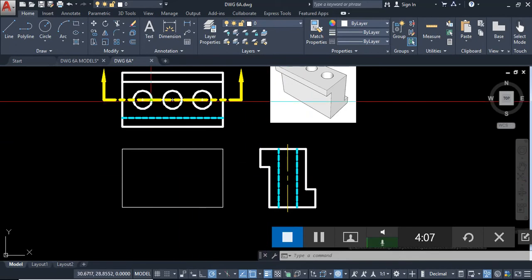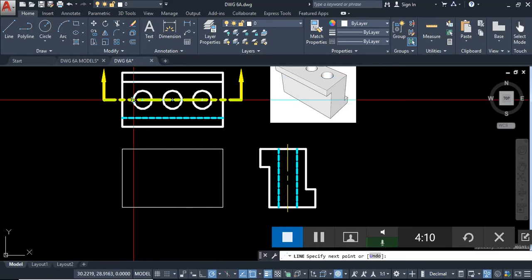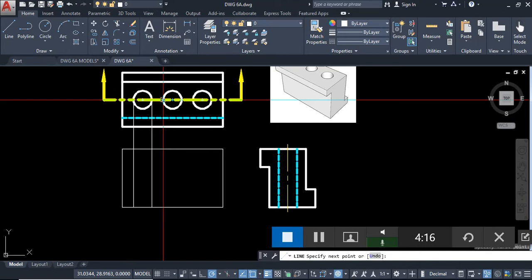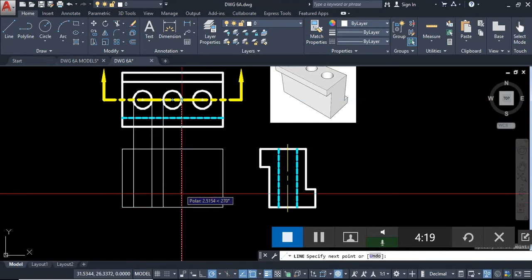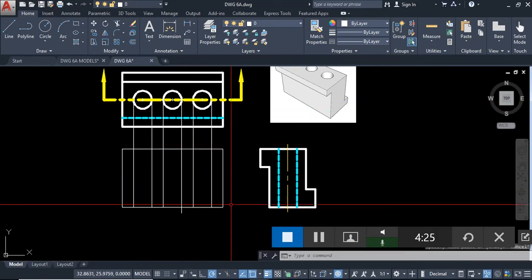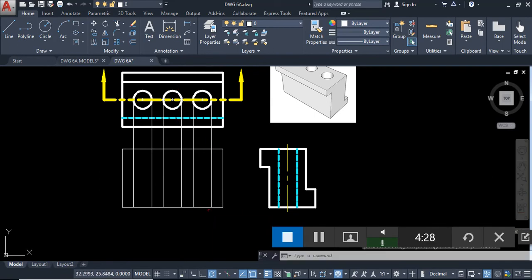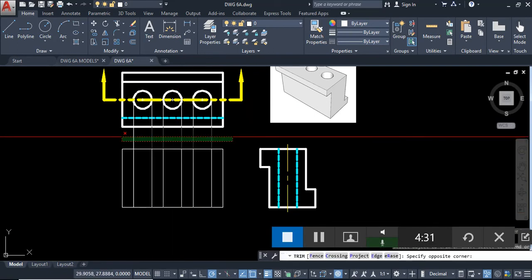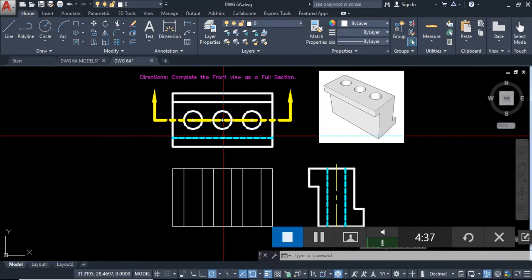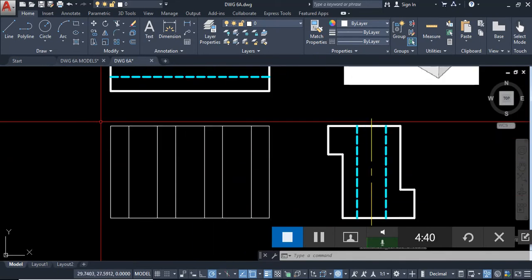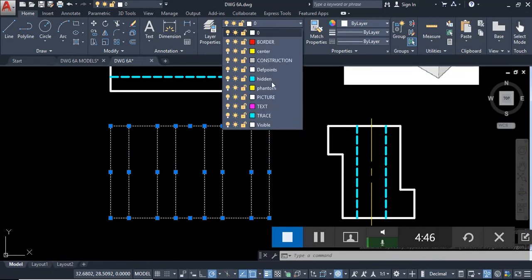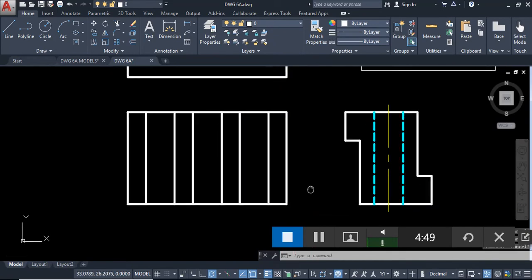Now, we have 3 tunnels. Tunnel 1, Tunnel 2, and Tunnel 3. So we can bring them down. Lightly project to show where these 3 tunnels are. And I won't need those projection lines anymore. But this is it. This is what I want. So these lines, you lay them out, figure out what you want, figure out where you want them. They are visible lines. They are object lines, so they should be nice and heavy.